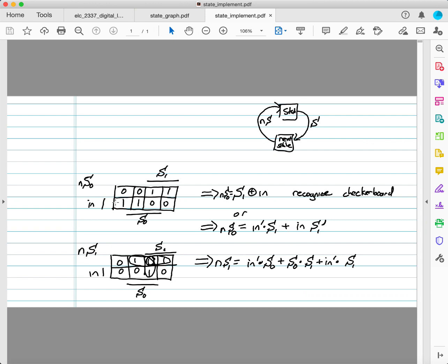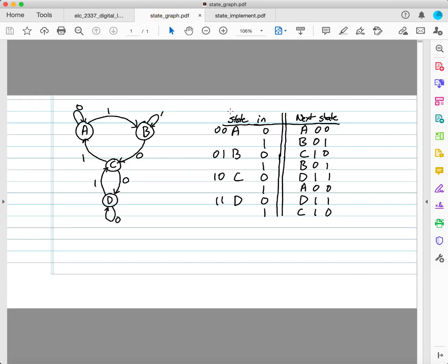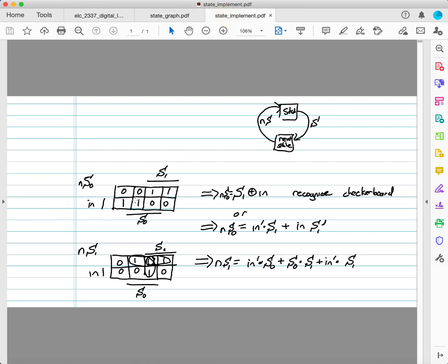Now, when you go to the next state 1, let's go back to the previous one so we have our table. When we look at the next state, state 1, that's the left bit, a little more complicated pattern: 0, 0, 1, 0, 1, 0, 1, 1. When we fill out the table, we have 0, 0, 1, 0, 1, 0 on the far side, remember gray code, and then 1, 1 down the middle. Our encirclements, you'll see it's kind of ugly, but there's 3 encirclements: a left one, a right one, and then the up down on the middle.